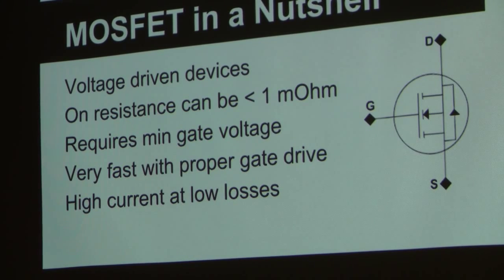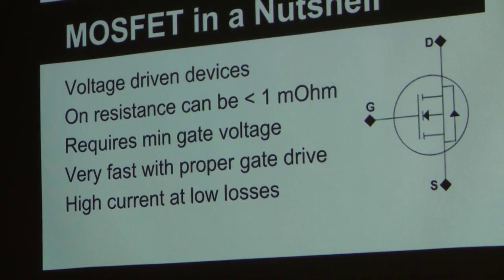But it also depends what voltage range you're looking at. Again, Moore's law is moving in our favor. But still, if you're wanting a 200 or 400 volt device, you're not going to find anything with an on-resistance of less than 5 or 6 milliohms.